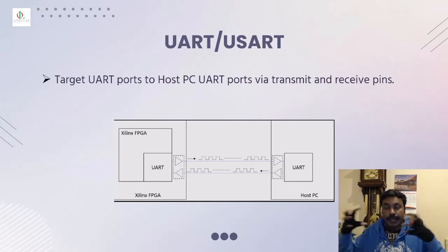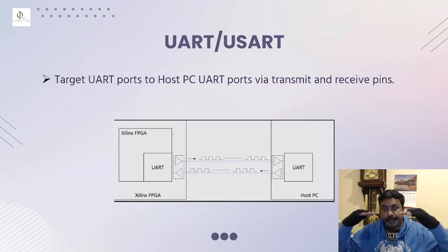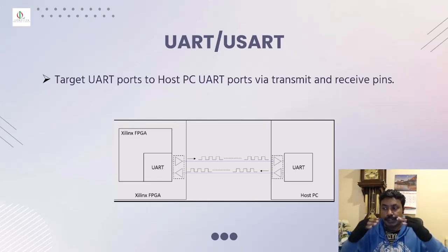Otherwise, there is no data communication, no transfer or receive happens, because for a start you will get plenty of errors and you won't even start to communicate to send any form of data. So please make sure both sit on the same baud rate, nothing changes, maintain the same speed. That's what really counts.